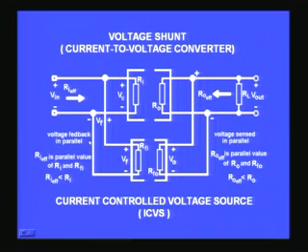And if you look at the input, you find this is also connected in shunt, that means in parallel. So if I look from here, the effect of that, as you would have immediately guessed, is also to reduce the effective resistance, because the voltage is fed back in parallel, so the effective resistance is the parallel value of RI, which is the Thevenin's equivalent resistance of your amplifier, and RFI, which is the input resistance of the feedback network. So they are coming in parallel, so that the input resistance is also effectively reduced. So both the input resistance and the output resistance are reduced.